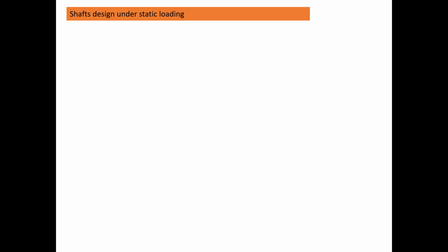Okay, now the stresses that affect the design of shafts under static loading, not fatigue or fluctuating, are kind of simpler than fatigue. Now recall the factor of safety. In general, it was defined as the strength, which can be SY or SUT, since we're only discussing static loading, divided by the maximum stress, which, let's assume, we have KT times sigma prime.